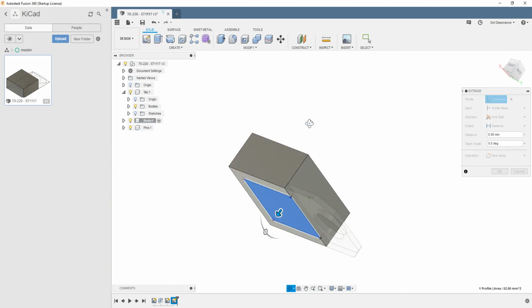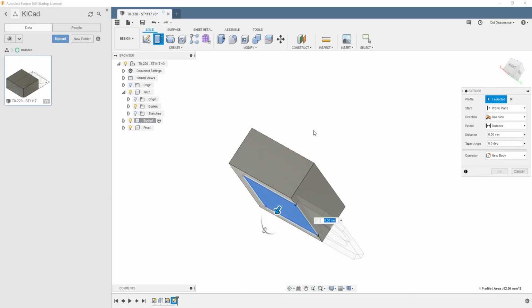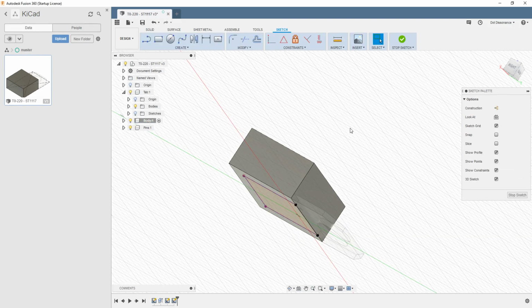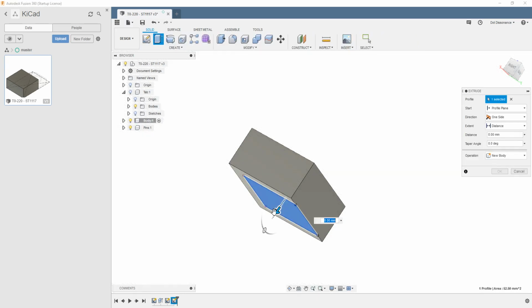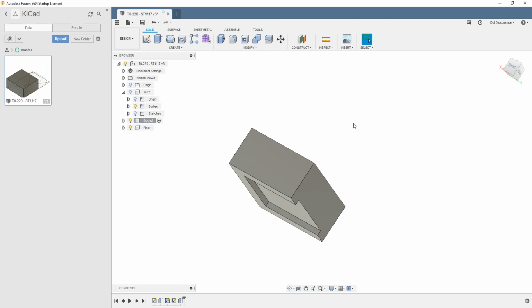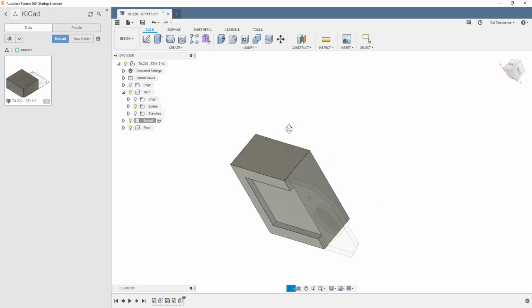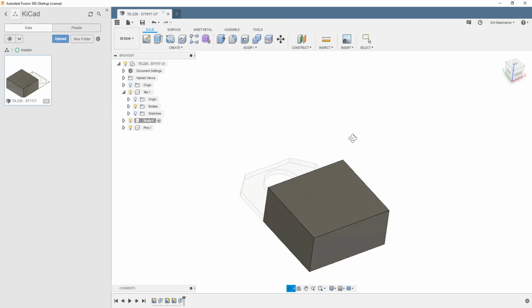This is a thing with this, right, that it will cut through the tab and the body, even though it's an assembly, different from other programs, it will cut through it. So unhide tab, and as a matter of fact, I'm not certain all the time that it didn't keep that in its mind that it needed to do that. So come back here, unhide tab, then hit extrude. Test that a little bit if you want. And then we'll say minus 0.6. And so then that has the same cutaway for the tab to fit into, or at least, you know, it looks like the actual part does.